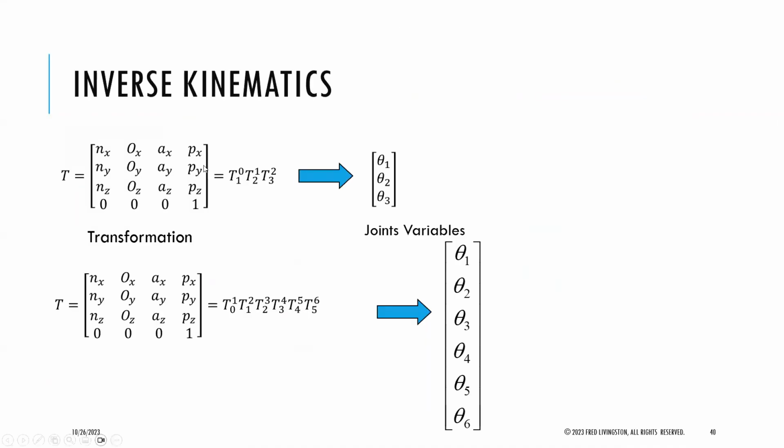So the inverse kinematics is going from the position, orientation, pose, 4x4 matrix, and I'm going to compute the joints. And for the n degree of freedom system here, most likely we're going to try to stick with 6. It's going to make the math a little bit easier when you try to invert, because remember, we could take the transpose or the inverse for a numerical solution. And sometimes you may not be able to compute the inverse kinematics. So it may actually give you multiple positions here.